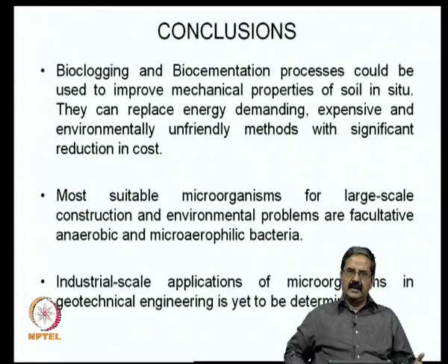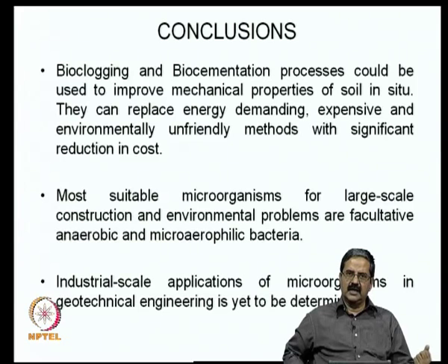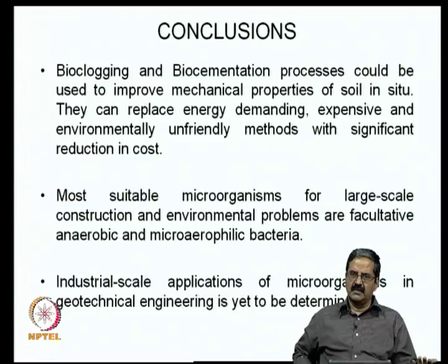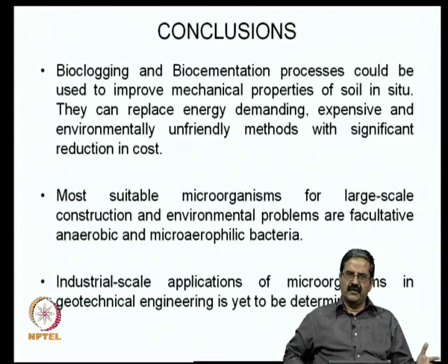they can be an industry within themselves, similar to the ground improvement technique companies that you have for grouting. One can specialize in trying to understand what type of soil you have in a particular application and look at what type of microbes should be used, what conditions are sufficient, and if the conditions are sufficient, you should do a field laboratory experiment and then come out with the dosage and other requirements and environmental conditions and find out the optimum benefit.